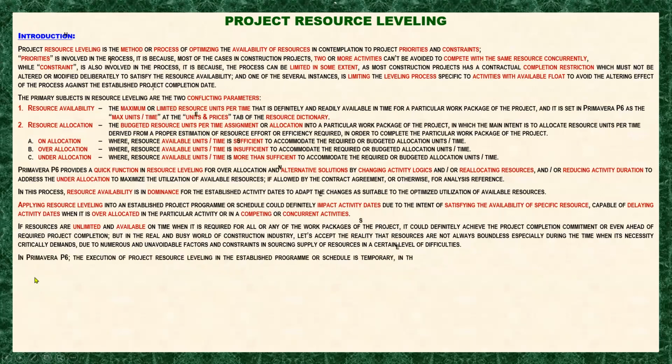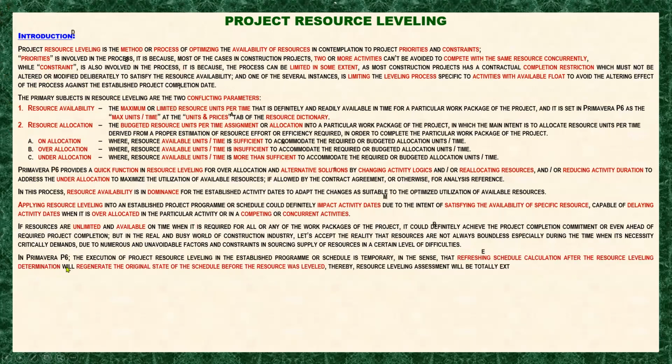Okay, moving forward. In Primavera P6, this is just to give you an overview before we proceed into the detailed discussion. In Primavera P6, the execution of resource leveling in the established program or schedule is temporary. Why temporary? Because a refreshing schedule calculation after the resource leveling will generate the original state of the schedule before the resources were leveled.